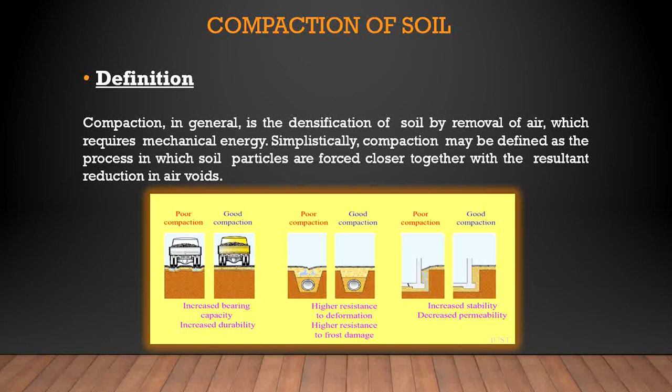Virtually any soil can be used for structural fill if it does not contain organic matter. Granular soils are capable of achieving high strength with relatively low volume changes, whereas properly compacted clay soils will develop relatively high strength and low permeabilities, which may be desirable features for earthen dams.